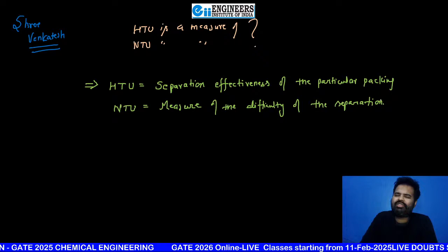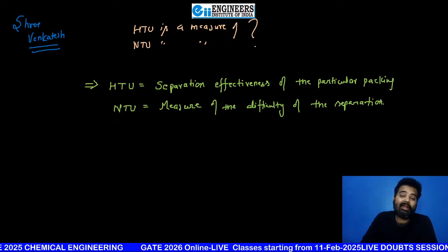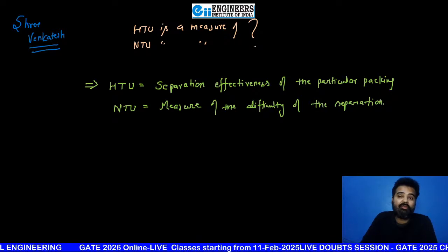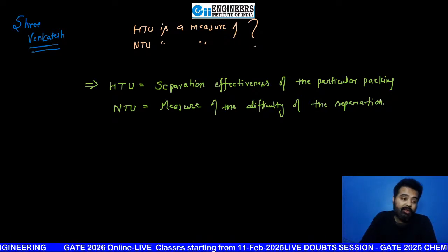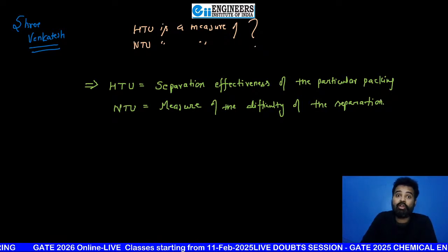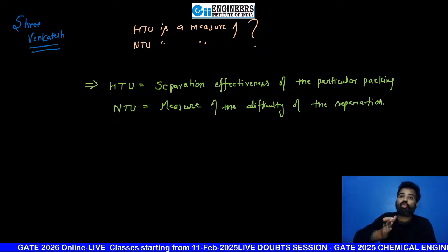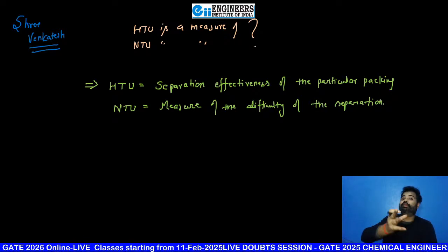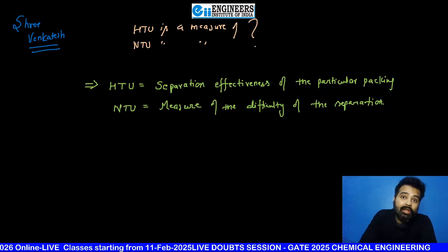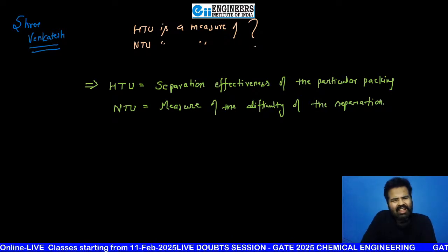If it is very dilute, even if it is not a 5% or 4% case, you can't just say dilute in the GATE examination, because the answer will differ a lot. We have solved PYQs and the answer will differ by 10 folds. There was a question with 5% and 1%. If I am assuming that small y, the value will change hugely, because for the inlet flow rate, if something like 10,000 is written, then G is 10,000 but Gs is 9500. So don't take risk in the last 11 days.